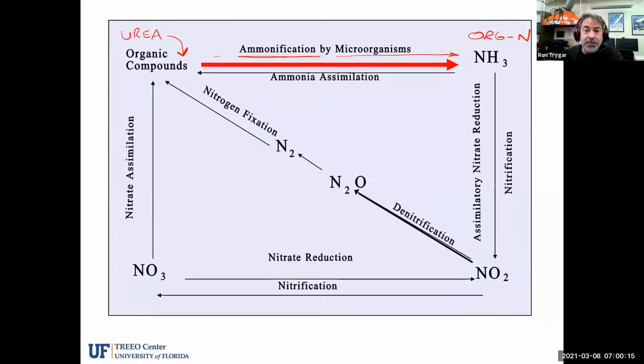If you have a subdivision that's very, very close to your wastewater treatment plant and a lot of homeowners there flush the toilet to get ready for work in the morning, you may have a large influx of organic nitrogen coming into the treatment plant early in the morning, because we have a lot of flow coming in early in the morning and it's in close proximity to the wastewater plant. So that organic nitrogen will also need to be converted or will be converted into ammonia inside the wastewater treatment plant.